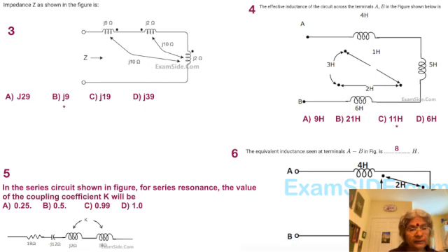Okay, so let's do it in the same manner. In the third problem, the effective impedance, in terms of reactances, will be given by J5 plus J2 plus J2, that is J9, and then from there we will remove the mutual inductance or add the mutual inductances by doubling them. In coil number 1 and 3, J5 and J2 are linked via a mutual inductance of J10, but the current is exiting the dotted terminal and entering the dotted terminal of one coil with respect to another. So we see that we have a minus J20 coming into the picture.